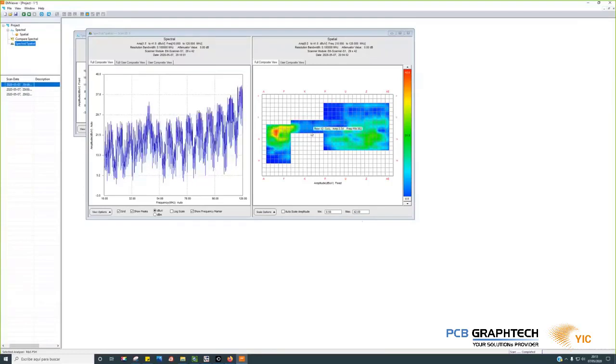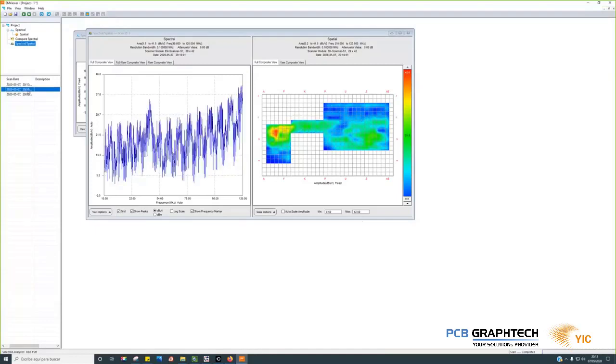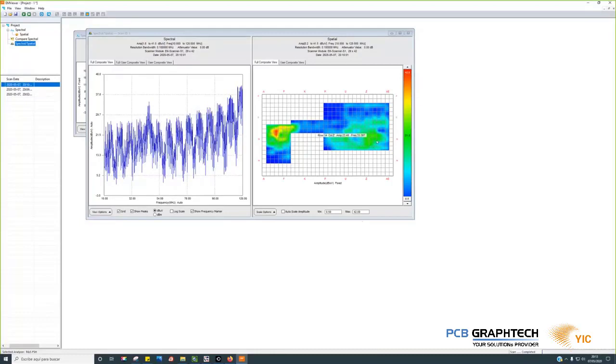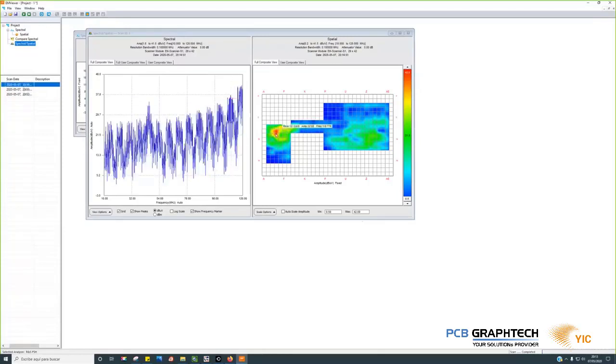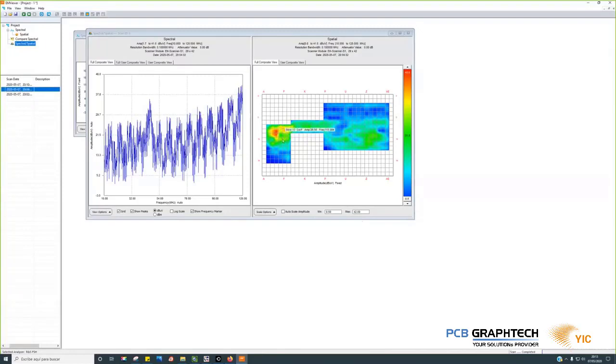You can see that in this area, in the cable, there is no energy going because of the effect of the ferrite. Obviously, in this area, the 11 megahertz, 33 megahertz, 50 megahertz is not changed because this is the activity of the digital circuit. And the activity in the buck converter is the same because there is no change here. I have not changed the design, so I have the energy here. So if, for example, you have another cable, you have the opportunity to radiate with the other cable. No?